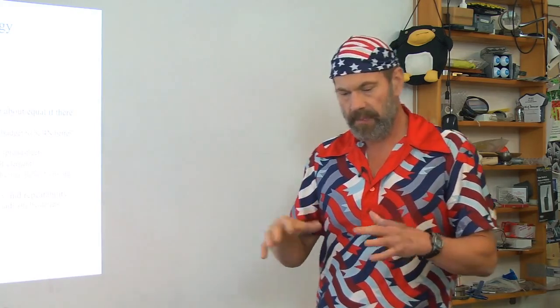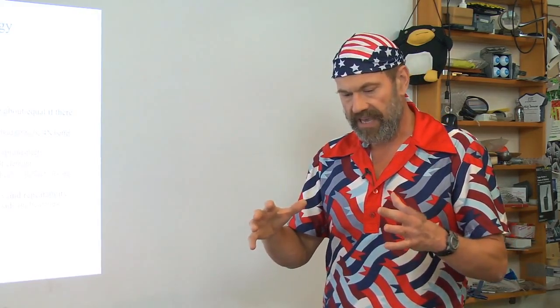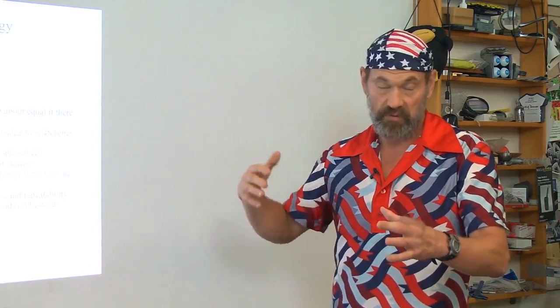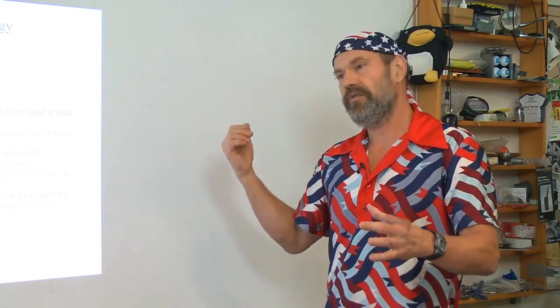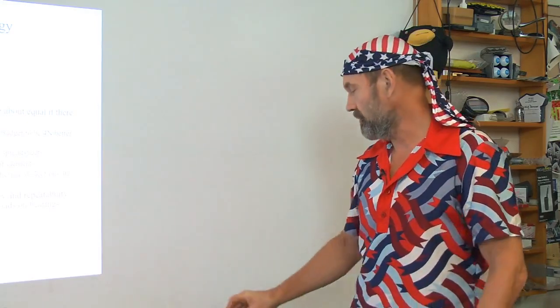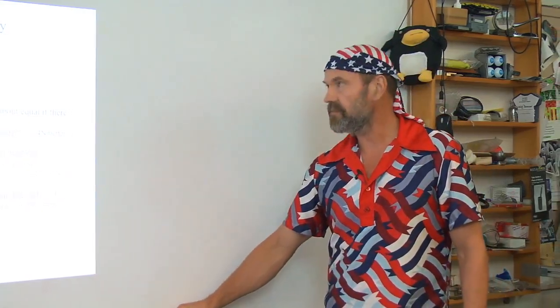They're also good for predicting misalignment loads on bearings, because you can use them to, say, model that these two bearings are aligned by this amount delta. And remember from our previous lecture, if you know the delta and the stiffness of the bearing, you can get the force on the bearing, which you then use for your load life calculations.